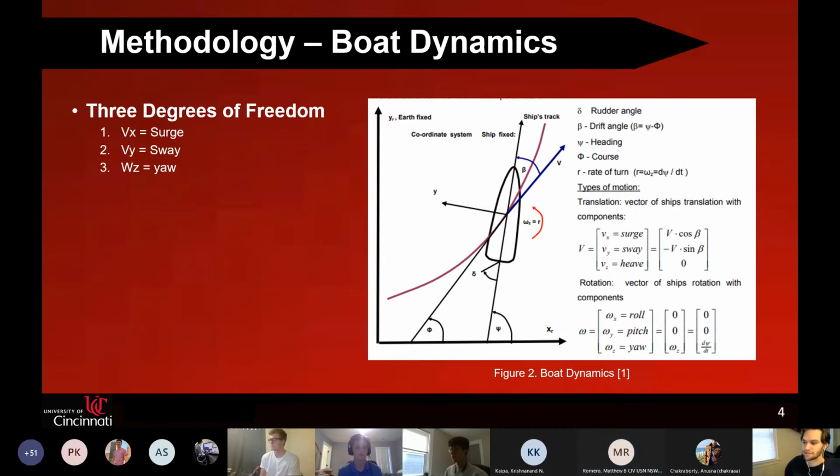Yeah, that's a good question. That was something we looked into after we had this simulation done for our current case studies. If the UAV is too close, it's obviously going to have to make a turn around and go back to those waypoints. If you turn the UAV all the way around, its left and right turning is going to be opposite of it moving in the positive north direction. So we had to change all the guidance systems to account for that condition and switch the left and right turning. So yes, it does have those capabilities, but whenever you turn around with our guidance system and try to go back to those waypoints,